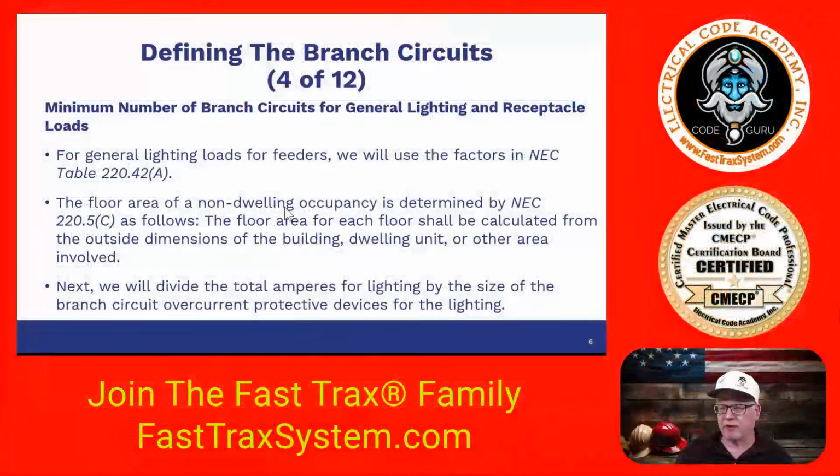Now, what's the first thing we need to do when we're determining the number of branch circuits that are going to be on the feeder panel? We're not doing a service calculation. The floor area of a non-dwelling occupancy is determined by 220.5(C) as follows. It says the floor area for each floor shall be calculated from the outside dimensions of the building, dwelling unit, or other area involved. We're not doing a dwelling unit right now.